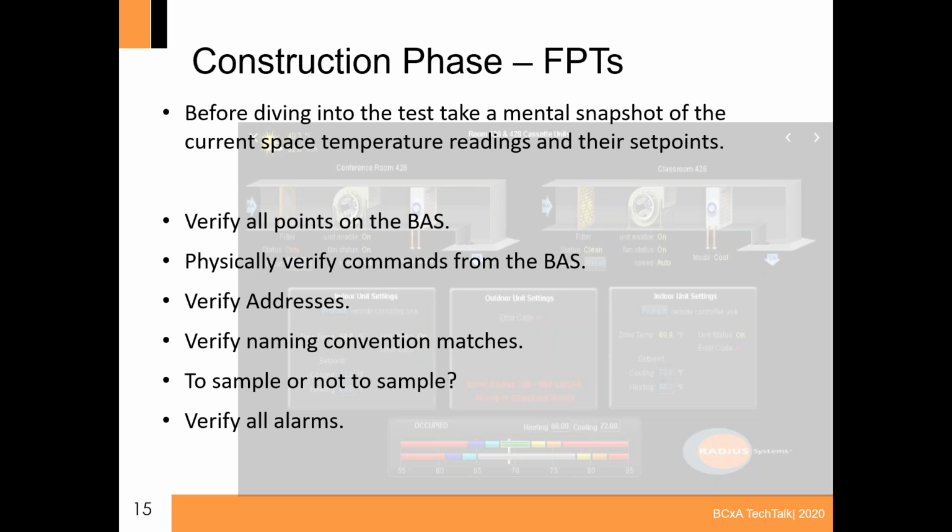And just knowing how VRFs operate, I was able to quickly diagnose a problem where they were set up straight from the manufacturer to control off of return air temperature. So these actually had a field fabricated mixed air plenum, and they still had that return air temperature upstream of that. Depending on where they put this outside air run depended on whether this return temperature was seeing 100% outside air, 50% outside air, or just return air, which is why some of them would go into full heat and some of them would control just fine.